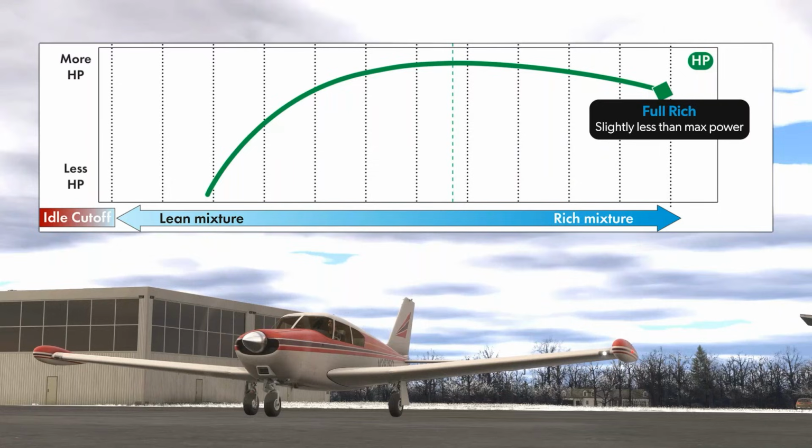This sounds like a lose-lose, right? We're producing less power and burning more fuel, but again, sometimes that's necessary. We'll come to that in a moment. Move to the left on this curve, pull the mixture knob out further. Eventually, we get to a point where horsepower is maximized. So this is our peak power point. And you'll note the vertical green dashed line here that marks this landmark. And that'll be a reference that stays on this chart as we go forward and add more to the chart.